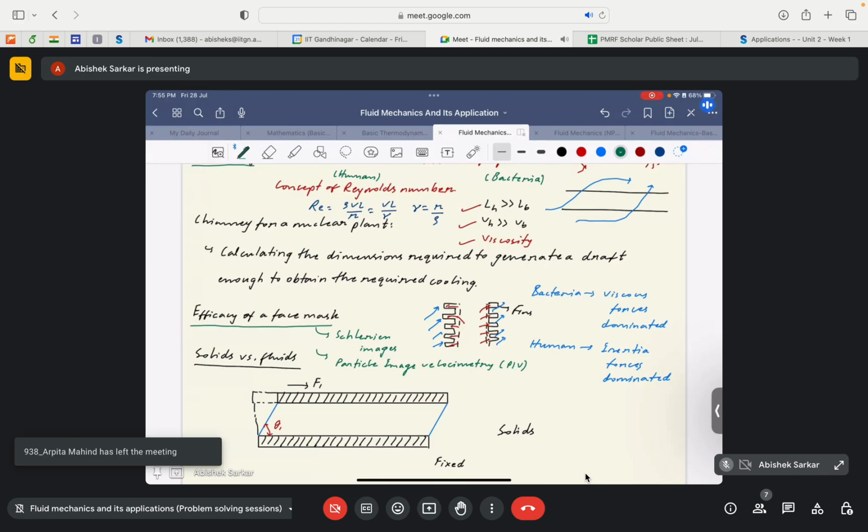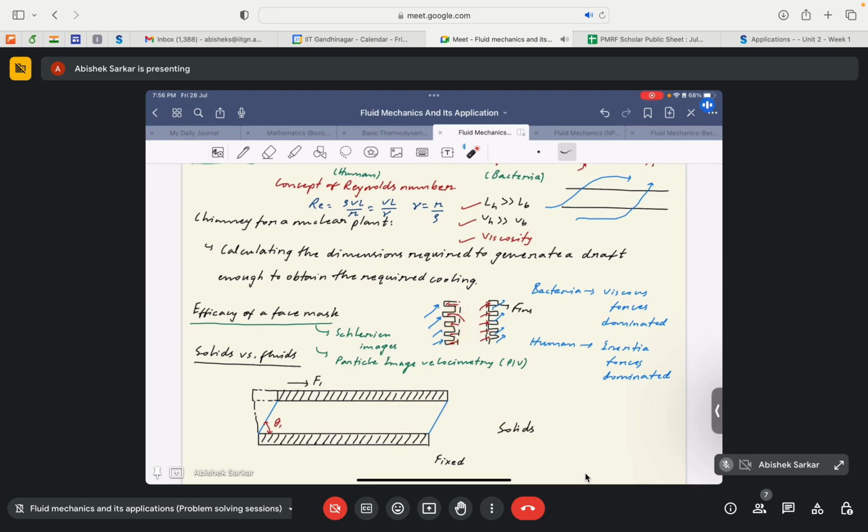Yes, you rightly pointed it out. So in the case of heat transfer from the inner surface of the cylinder to the outer surface of the fin, it would be conduction. That's right. But from the outer surface of the fin to the outer air, it would be convection. And if you know, convection is a combination of both advection and diffusion, right? So in the case of convection, the advection would dominate. That is, the bulk motion of the fluid that carries the heat would dominate, and thus we say that it is the bulk motion of fluid that helps in dissipating the heat from the outer surface of the fin, right? But as you rightly pointed it out, from the inner surface, it is conduction through which the heat is being dissipated from the inner surface of the cylinder to the outer surface of the fin.